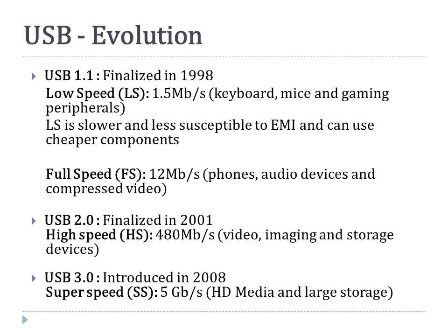The next evolution was USB 2.0, which became highly popular, and it supports data rates up to 480 megabits per second and can be used for video, imaging or storage devices where a large amount of data transfer takes place. With the evolution of technology, technology scaling and Moore's law, new kinds of media were developed, like HD media, and portable hard drives became large enough to store up to terabytes of data. So this all required a much faster serial interface, and USB 3.0 was developed in 2008, and it supports speeds up to 5 gigabits per second and is called SuperSpeed USB.